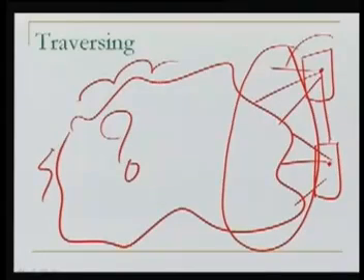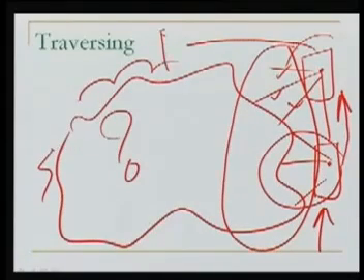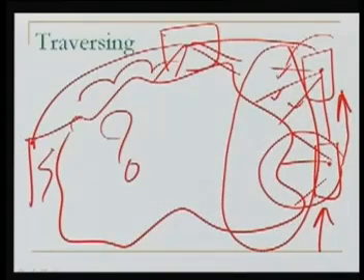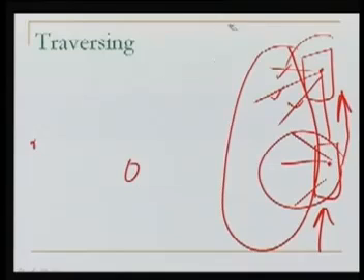This can be realized if we replicate the same process. We occupied one point, made some rays, then moved to the second point and drew some rays again, then possibly moved to the third point and drew some more rays, then the fourth point, again drawing rays. That way we are forming a traverse. So this method of plotting is called traversing.